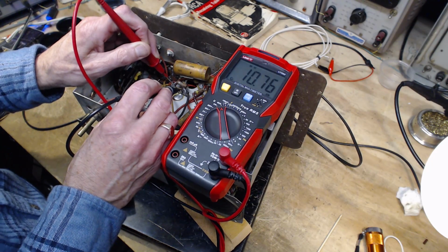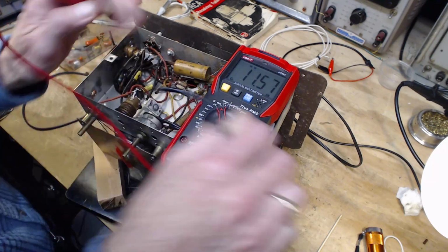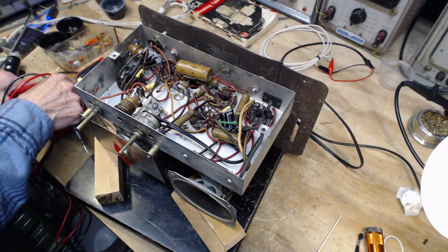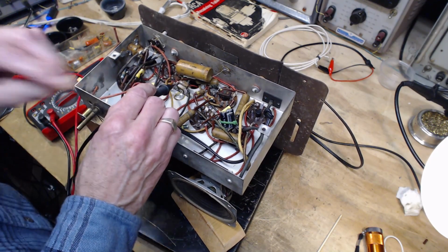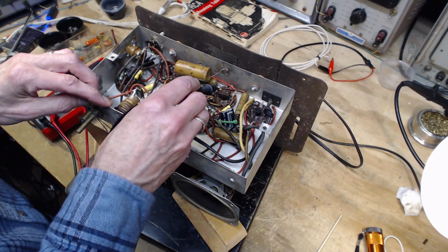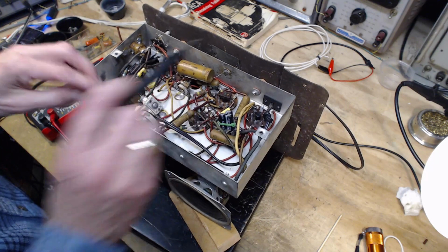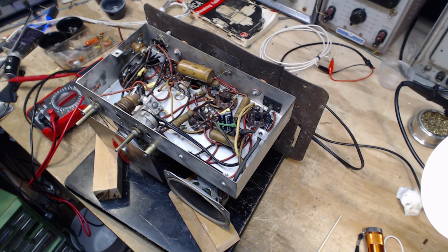So, I mean, this is a whopper of a resistor. There's nothing else like it in this radio. This has to be, for many reasons, that has to be the resistor. So we have the low impedance side, the high impedance side, and the high impedance side is a capacitor tied to B minus. This has to be the capacitor I'm after. Okay. Well, it sounds very reasonable. Very, very reasonable sounding.